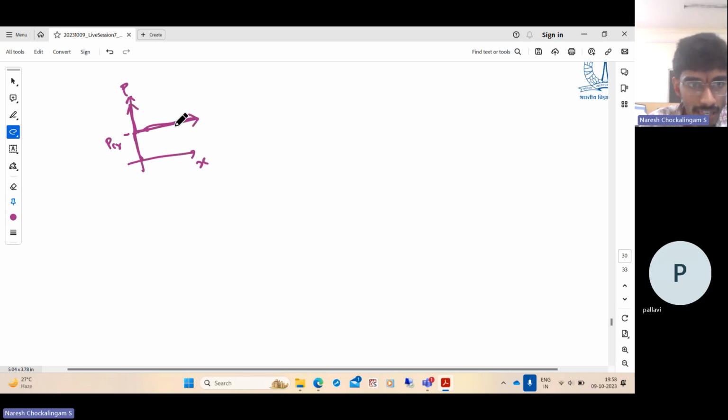So this is called a bifurcation point. So this is the path. As you increase the load from 0 to P critical, for P less than P critical, there is no other equilibrium configuration. You only have this one. But for P greater than P critical, you can either have this or this. But this is unstable. So if you slightly disturb, even if you maintain the bar at this stage, it will come back to this.